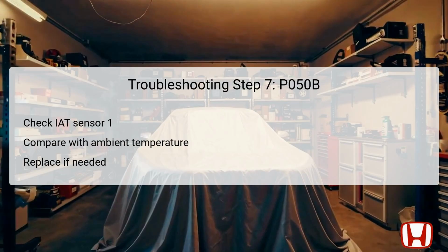However, if no significant difference is detected, the IAT sensor is functioning correctly, and further diagnostic steps should be taken, such as inspecting the throttle body for dirt or damage.